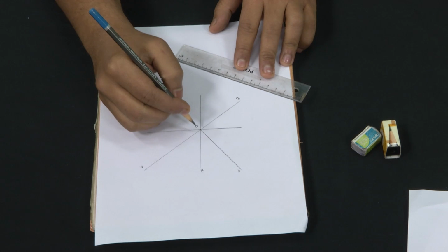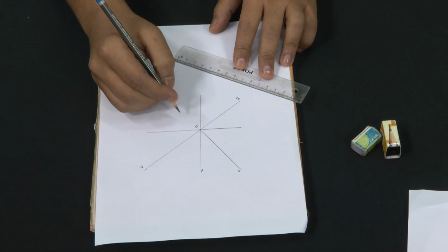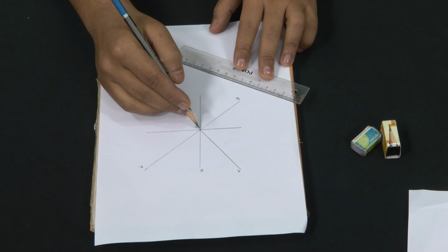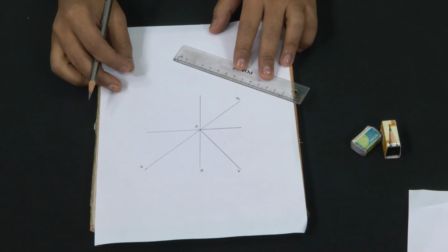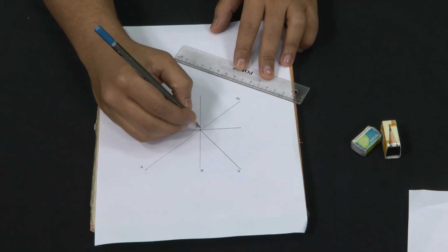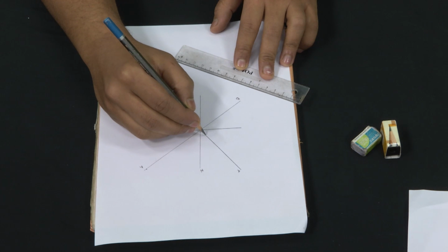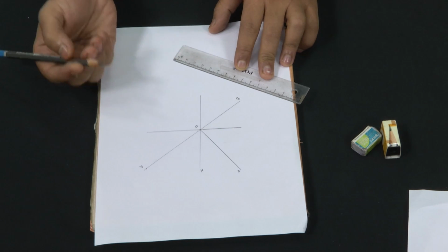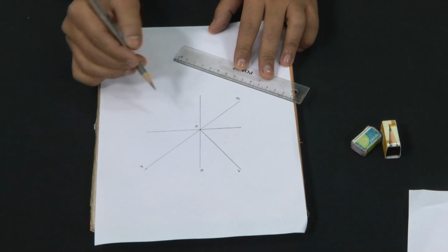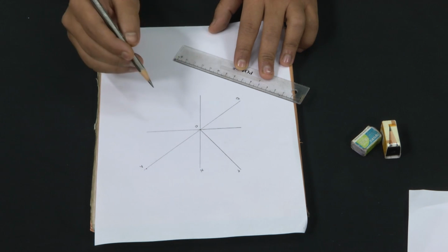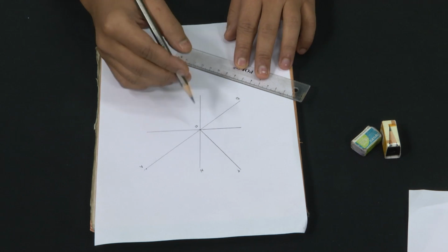Now, I know the scale of the problem is 1 centimeter equals 100 meters, and I also know the dip of my bed is 48°. So, clearly I now have to find a point on the line OP, and when I find the point I have to draw a line parallel to AB which will be another strike line or stratum contour, and so from two strike lines or stratum contours clearly we will get the orientation of the bed.